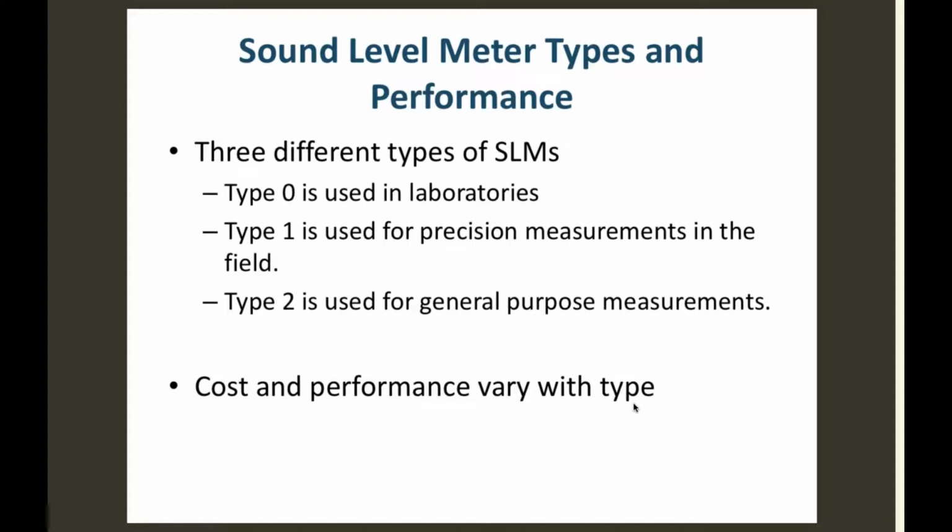If I have a device to measure carbon monoxide in my hand, a direct reading device like an indoor air quality monitor, and I can read on there an instantaneous reading of what the level of carbon monoxide is, that's not my dose. That's just the current level, right? The dose is what you've been exposed to while you've been in that environment, and it's time weighted over that period.